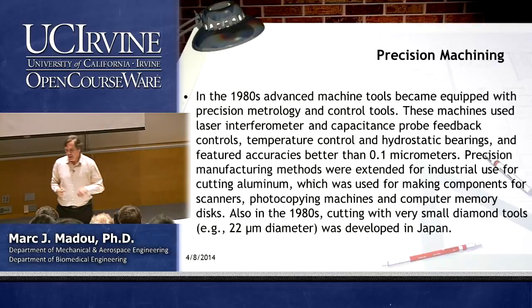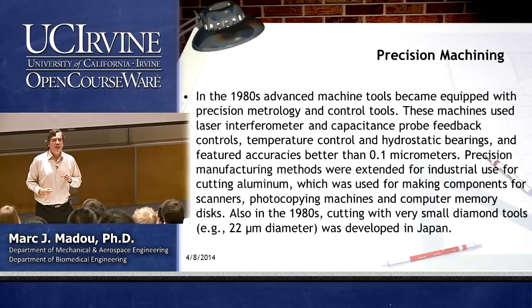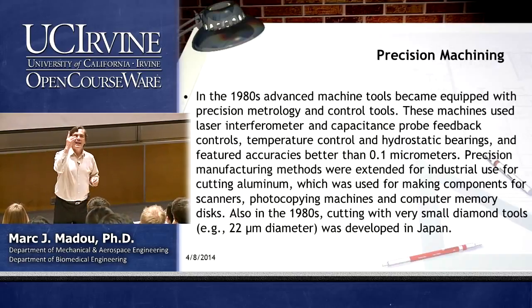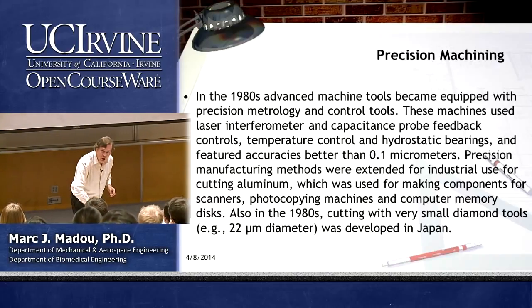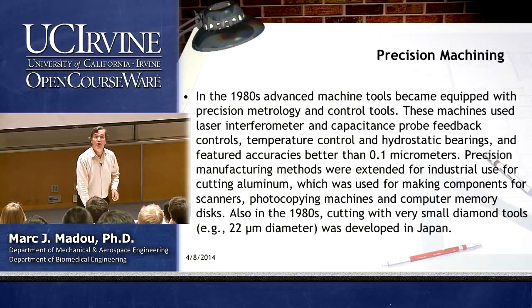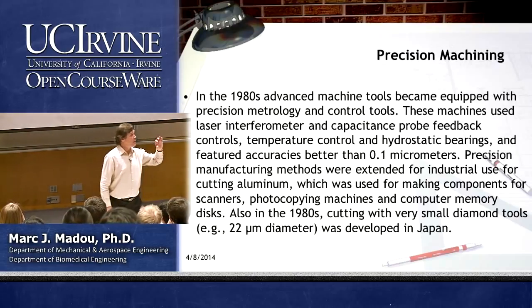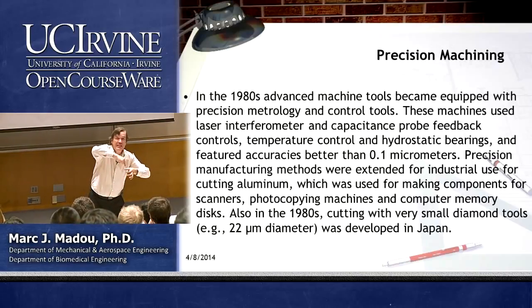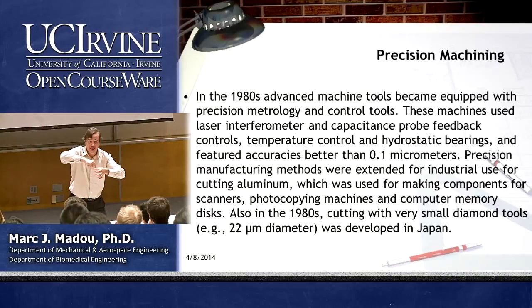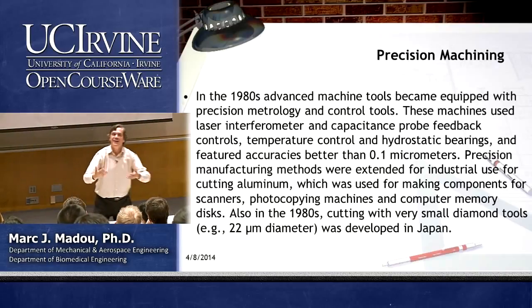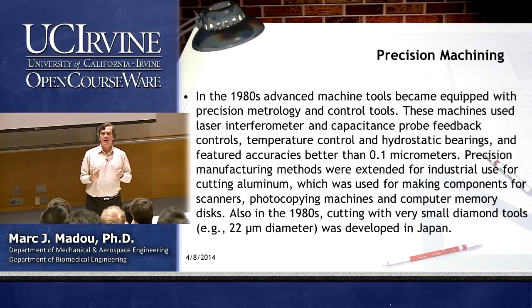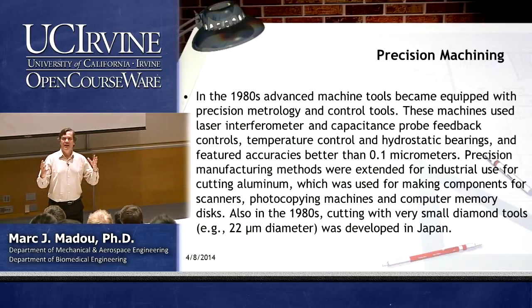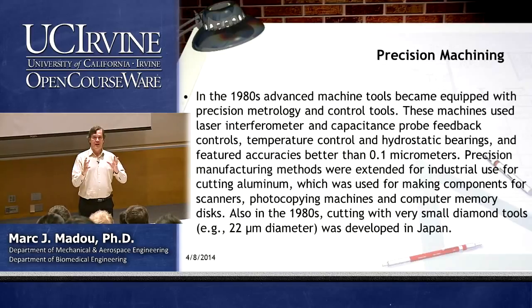The thing is this. In mechanical machining, you can do tremendously accurate things, but only in one axis, in the z-axis. The cutting itself of the piece will be much bigger. The mask will be, let's say, 1 millimeter. You can cut that. But the features that you carve out in the z direction by going up and down, at different angles, that you can do to 1 to 2 nanometers. So when people compare lithography results and mechanical machining, you have to be very careful what you're really talking about.